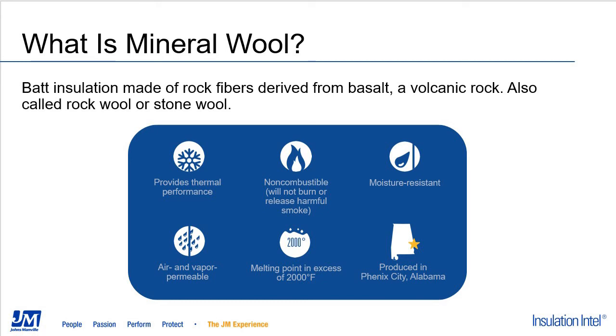When it comes to mineral wool, there's a lot of advertising out there about its sound properties, and mineral wool is an exceptional sound attenuation product. But the fact is that fiberglass typically performs just as well as mineral wool does when it comes to sound. The human ear, when installed properly, cannot tell the difference between a mineral wool or a fiberglass insulation. Mineral wool has very effective thermal performance, but so does fiberglass. So that leaves us really with fire. Fire is where mineral wool excels, and that's really what it comes down to as to why you would use mineral wool instead of fiberglass.